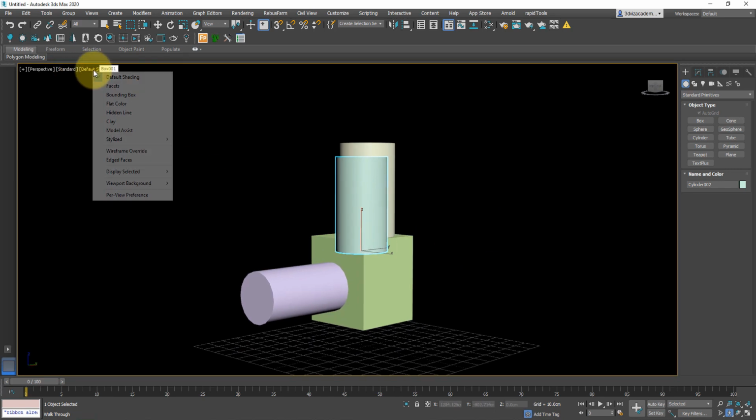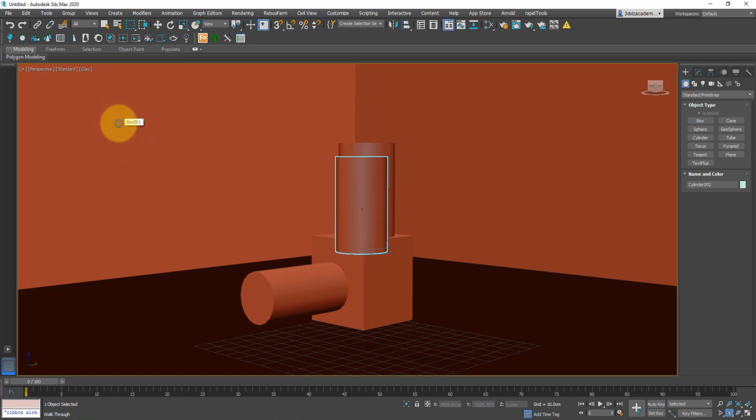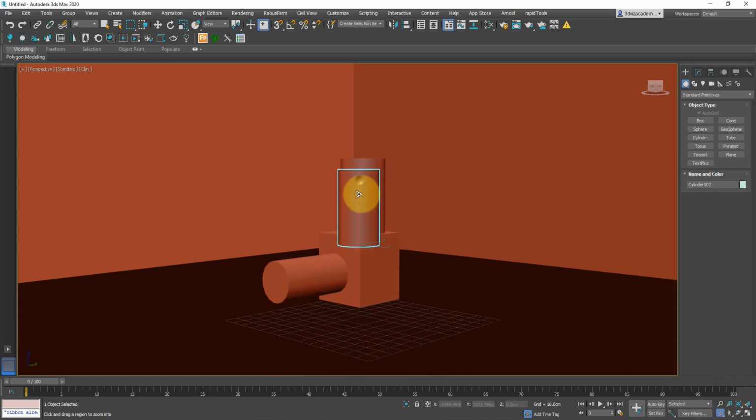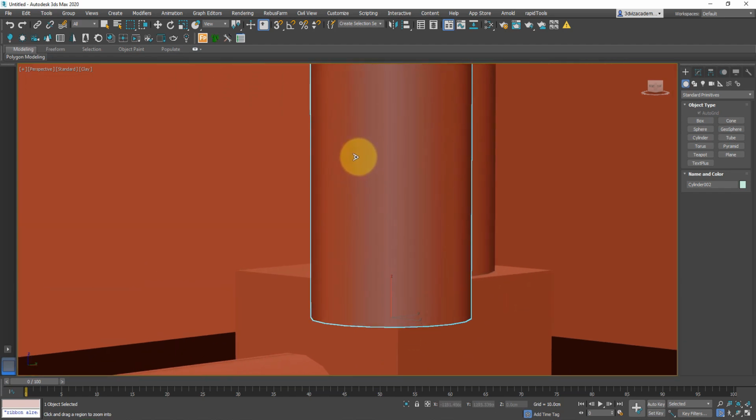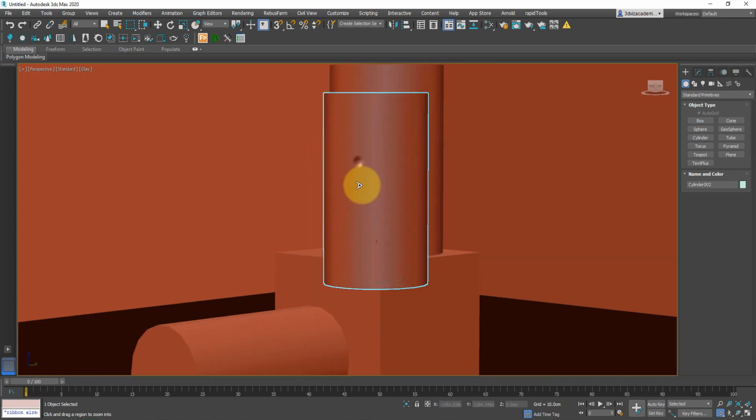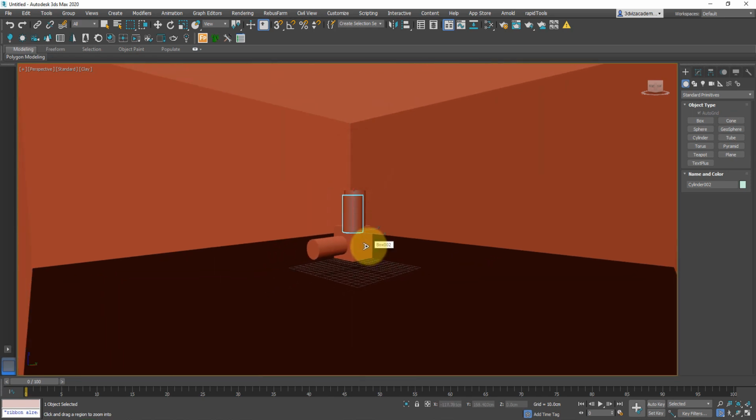Now, as you can see, again, we don't really have much to work with, and we cannot really see anything else than the walls. So this is when your field of view is going to be very handy. We can zoom out this way by changing our field of view. So right now we have pretty wide angle, and as you can see, we cover this whole room at the same time. You can also zoom in this way, which is going to give you this more filmic look. Most of the cases you want to keep your viewport as wide as you need, because in this case it's just going to be easier to navigate in your scene.